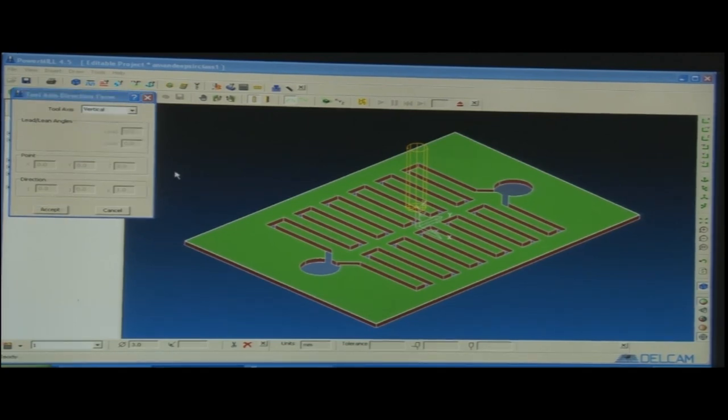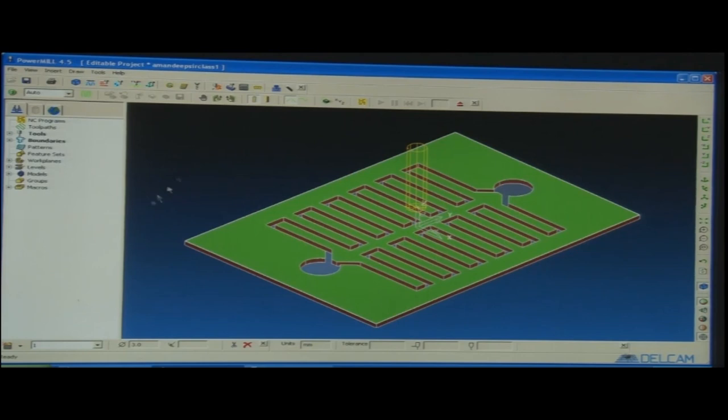Because this is normally a vertical milling machine that we are working on, I will keep this option as tool axis vertical. It is also a 3 axis milling machine. We do not have 3+1 or 3+2 options in the machine that we will work on. So, we will just pick vertical. Once everything is done, I keep saving my options as I go. So, next is work planes.